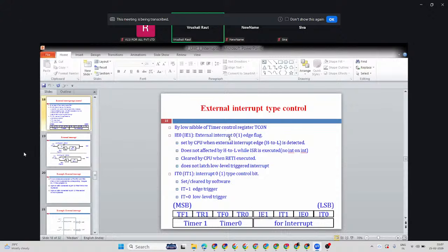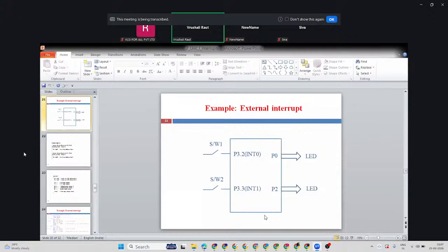And light, we are turning on the light, means what? We are closing the switch, we are pressing the switch. This switch is pressed, means what signal is going here? High signal is going here. If you know INT bar is there, this is going to be high, means internally inside what is going? Low is going inside because it is INT bar.